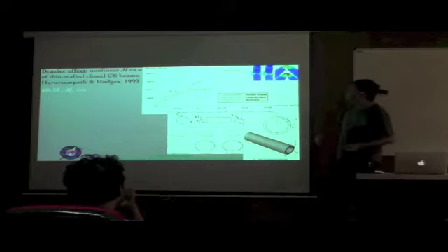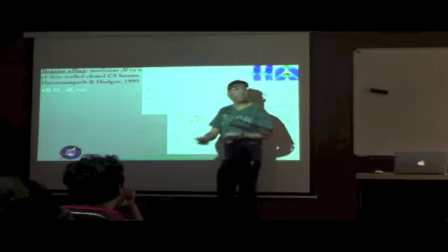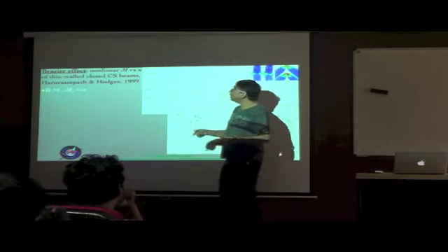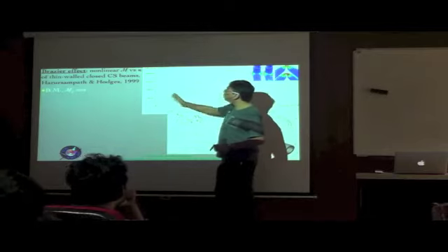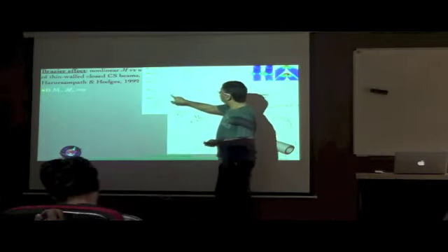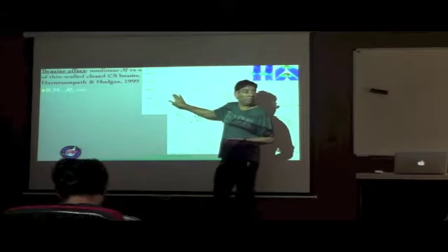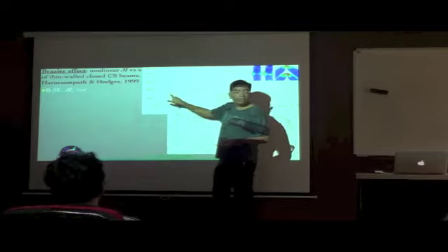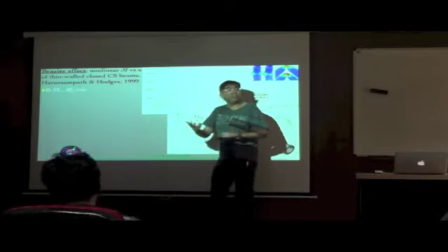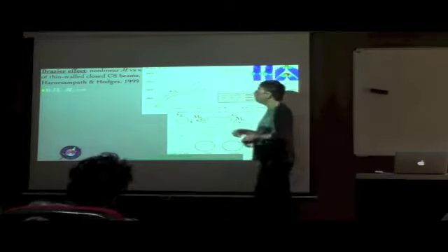Depending on all these, you will have a possibility that either this limit moment instability might come earlier than the other modes of failure that we discussed, or those might occur prior to this. Irrespective of what it is, the nonlinear behavior is important, because most of these failures, even if it's material failure and/or local buckling, etc., will typically happen in this particular range. If you don't take this nonlinear behavior into account, even the prediction of the other modes of failure like the material failure and/or local buckling can be erroneous.